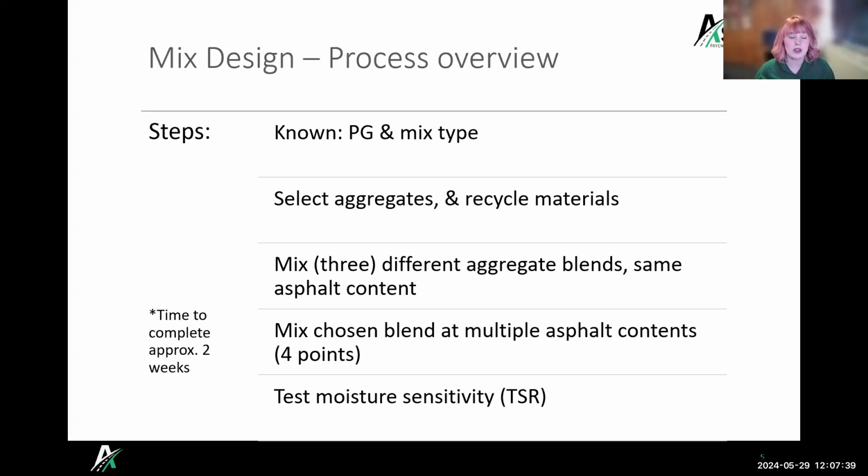So what happens if a contractor gives me a mix design that they already have, like maybe they used it on a different project? Is that okay? It sure can be, as long as it's for the same mix, because each mix design is specific to that mix. So as long as that mix is being specified on a different job for that same mixture with the same liquid and all that, then you should be able to accept that.